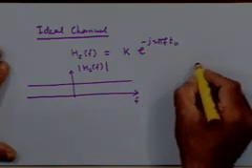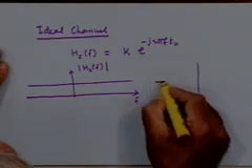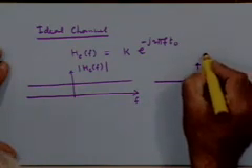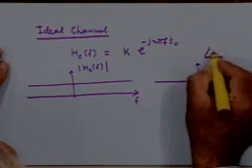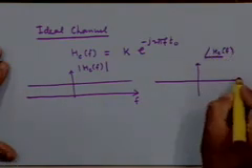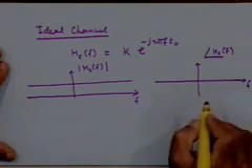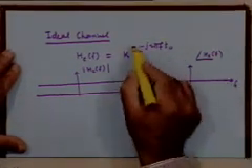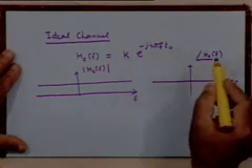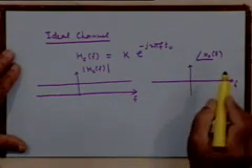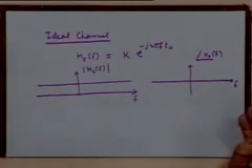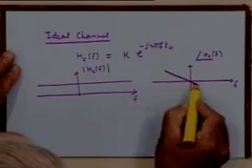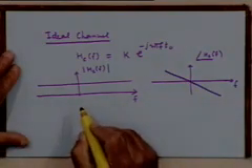And what are we expecting from it in terms of phase characteristics? Anyone? What will be the angle of Hc(f)? What kind of characteristics are we expecting as a function of frequency? The exponent here, which is minus j2 pi f t0, as a function of frequency. It's a straight line with a negative slope.